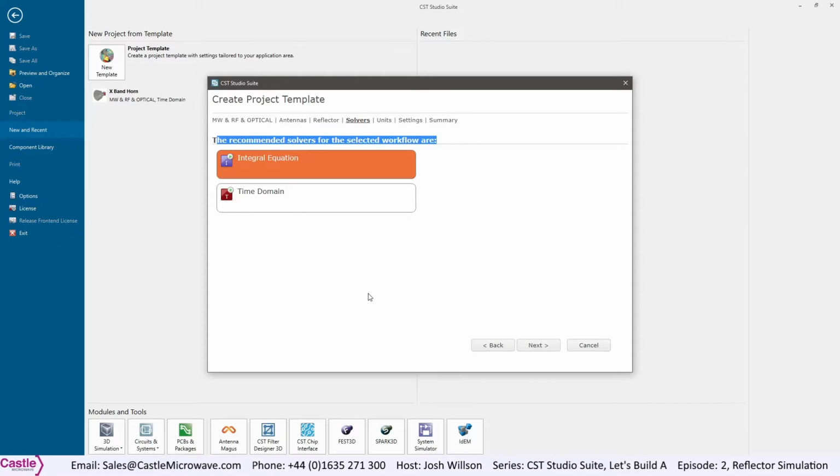The integral equation solver is of special interest for electrically large models. The discretization of the calculation area is reduced to the object's boundaries, and thus leads to a linear equation system with fewer unknowns than volume methods. For calculation efficiency, the equation system is solved by the multi-level fast multipole method for electrically large models. For the direct solver, the system matrix is dense.